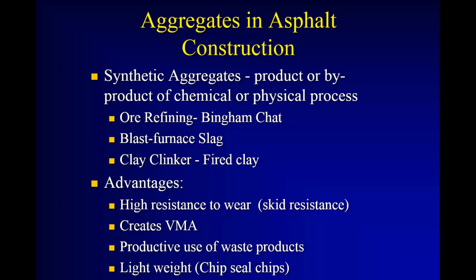There are a lot of synthetic aggregates as well. You get in the Chicago area, Gary, Indiana area, there's a lot of slag from iron production. And interestingly enough, Ross Benson, who used to work with DAPA teaching these classes 20 years ago, worked with a consultant that worked with the Illinois Tollway Authority, still does. They used a lot of that iron ore material in their surface courses because obviously Chicago's in a mixed environment area, a lot of freeze thaw, snow, ice, and so forth. It's very high in friction.